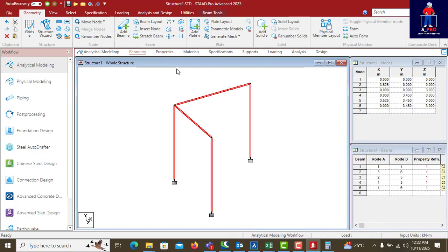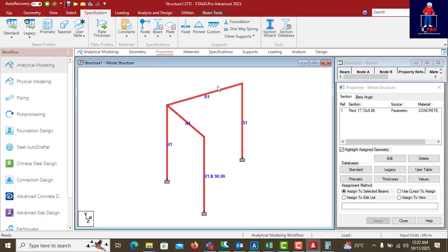While you are modeling, your beam can be 225 by 450, fine. It is your analysis that will determine the required depth of beam, because the ones that are not appropriately sized will fail. So whatever you're using as your beam size is tentative.